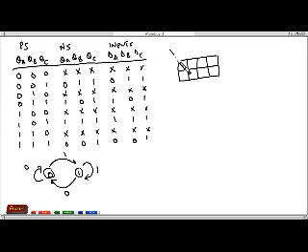So the K-map has 3 inputs: QA, QB, and QC. 0, 0, 0, 0, 1, 1, 0, 1, 1, then 0, 1. We first fit in the values of the don't cares at 0, 0, 0, 0, 1, 0, 1, 0, 0, and 1, 1, 0. So these are the locations of the don't care terms in our given design.